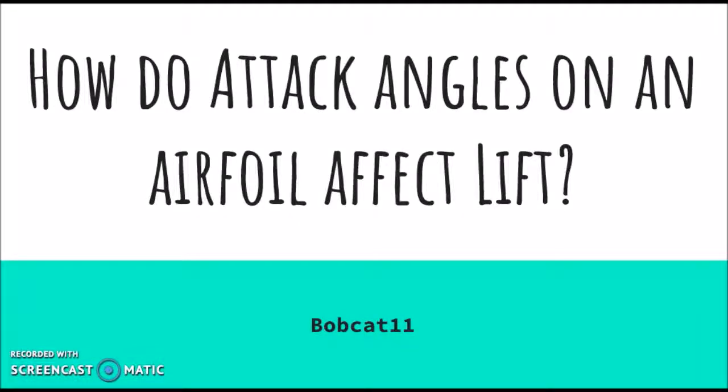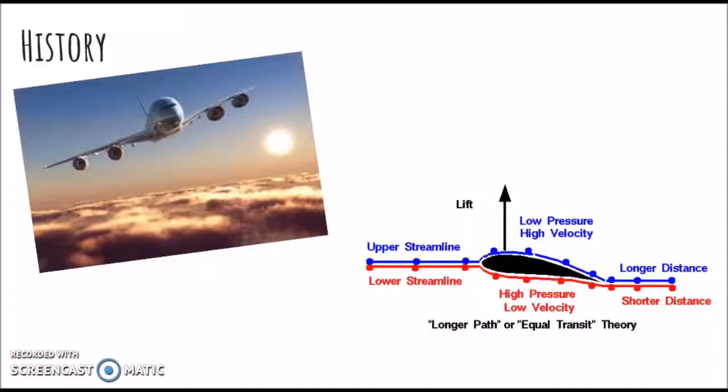The fluid application being studied is the flow over an airfoil and the effects of increasing angles of attack. The story of the airfoil is as old as the Wright brothers. The main purpose of the airfoil is to create lift, which is mostly due to the angle of attack and shape of the airfoil. When orientated at a suitable angle, the airfoil deflects the oncoming air to produce a higher